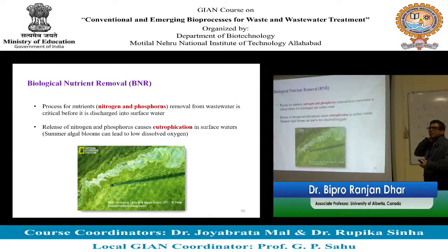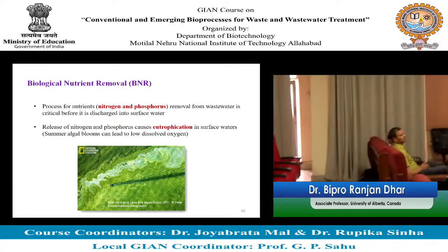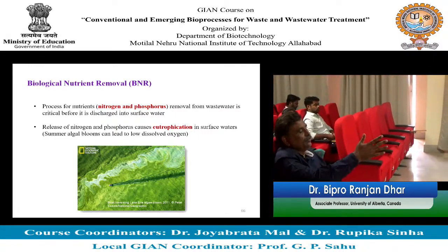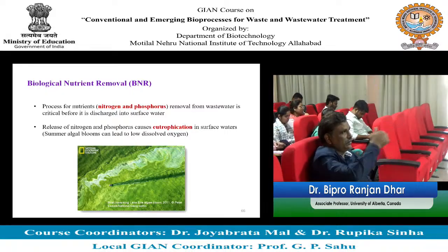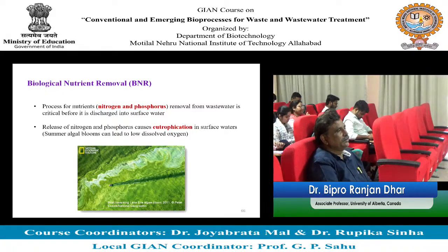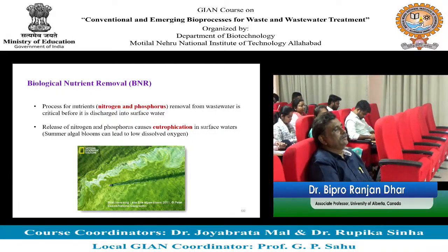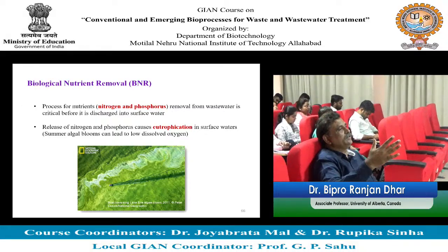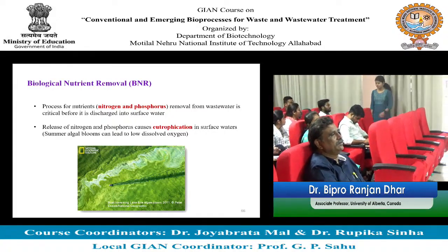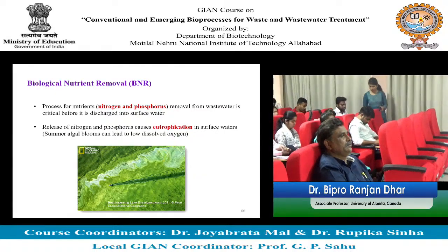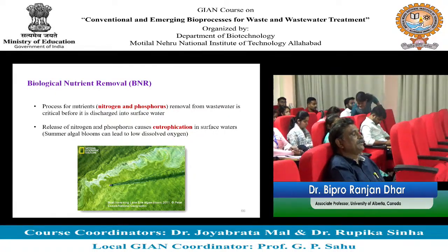Most of the time, majority of the wastewater, yes, please. Earlier we were doing the biological process, sir. Earlier we were using the biological process. Do we need to add any supplemental nutrients? No, typically we don't. We consider that wastewater contains enough nutrients that can be utilized by the microbial cells. Some micronutrients are required, like iron, manganese. No, we typically don't add them. They are micronutrients, right? So you don't need a lot that you need to provide from outside.